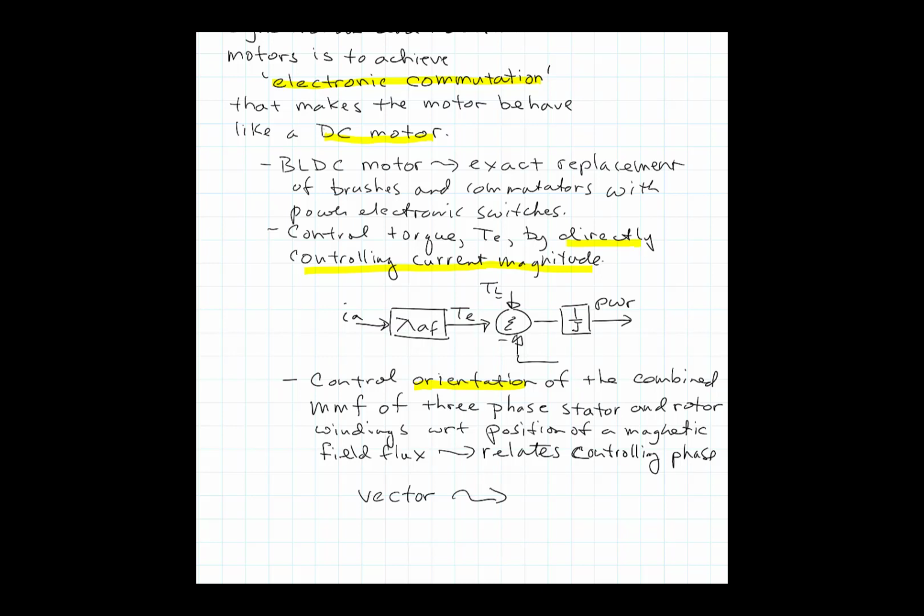Really controlling a vector for, let's say, the stator current, or a stator current vector, and I will give you a little more insight into how this can correlate to three-phase windings. But e^(jωe t), that's the synchronous frequency that you can control with the inverter. Remember, in the DC machine, ωe is 0, so the synchronous frequency is 0.